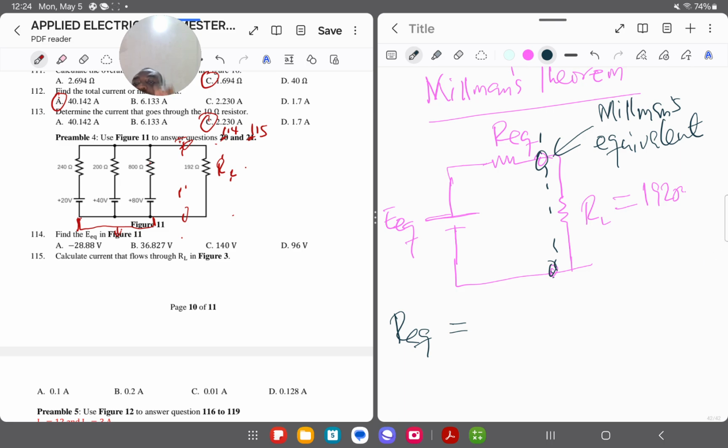To a current source in parallel with a resistor. So if we convert each branch, we have 3 of them, right? So you now have what? These resistors are now going to be in parallel with each other. So as a result, the equivalent resistance that we will be calculating here is just going to be, and they are all going to be in parallel, right?